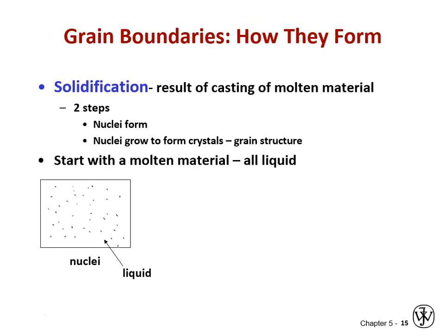In a grain boundary, the crystal on one side of the boundary has no relationship to the crystal on the other side, other than that they are the same crystal system and material. Their orientation is totally random relative to one another. And you get this by solidification or nucleation of a new crystal structure from an old one. The easiest way to envision this is the nucleation of a solid material in a liquid, where you'll start by, as you say, increasing pressure, dropping temperature. You'll nucleate new solid crystals in their parent melt.